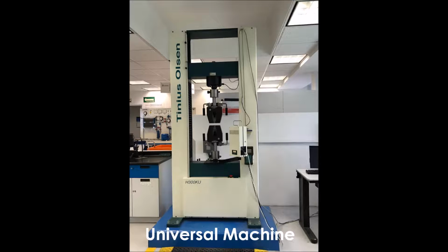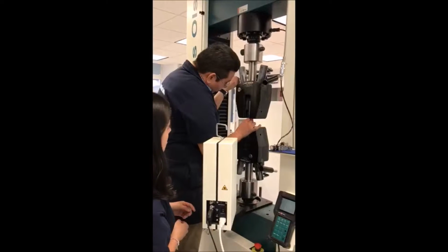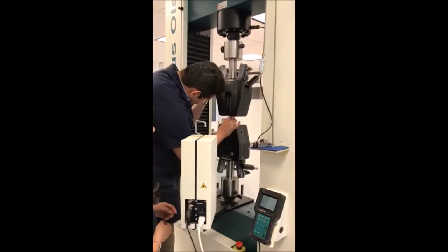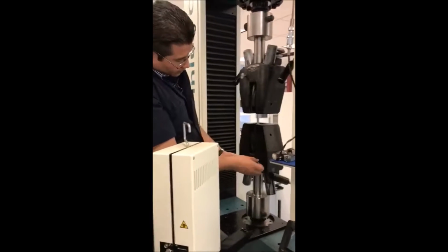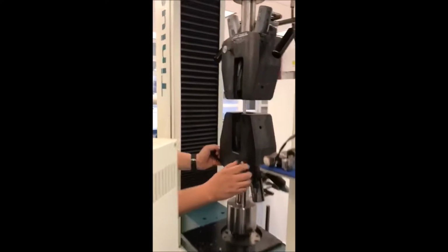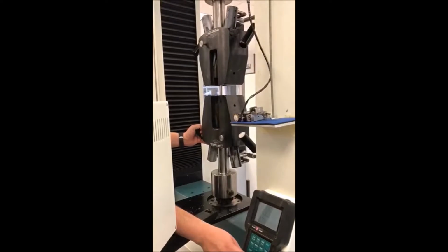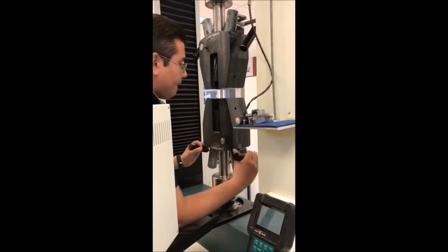For the experimental procedure, the equipment we used was a universal machine and a vernier. To begin with, we registered the dimensions and the necessary information of the steel and aluminum test tubes to complete the first chart in the practice. Then, we set the steel test tube on the universal machine and adjusted it to a correct position using a portable control, and we tagged it.